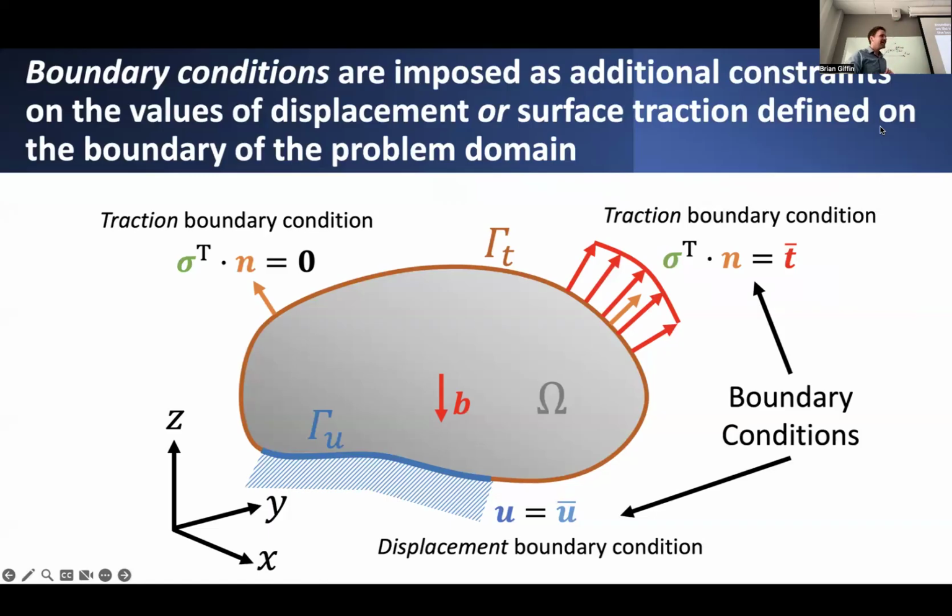So it's a vector. And it basically means we can only really constrain or impose constraints on 3 components of stress, those that are exposed on this kind of exterior surface of the body. So we can impose traction boundary conditions that basically say that whatever components of stress are exposed on this surface have to be equal to some prescribed value. And anywhere else where we're not specifically saying that it's equal to T bar, some prescribed value of traction, it's kind of assumed that, if we're not constraining displacement, we're not kind of putting any load on it, those extra areas on the rest of the body are kind of free surfaces.